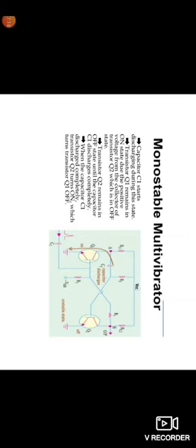The current will move towards the base of the transistor Q1, so that Q1 remains in the on state due to the positive voltage from the collector of the transistor Q2, which is in the off state. Transistor Q2 remains in the off state until the capacitor C1 discharges completely. Next, when the capacitor C1 has discharged completely, the transistor Q2 turns on, and transistor Q1 turns off. This is case 2.